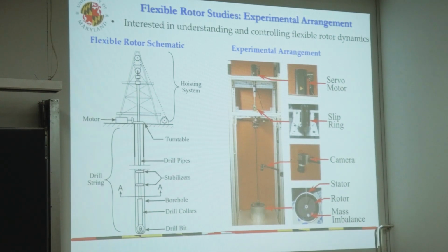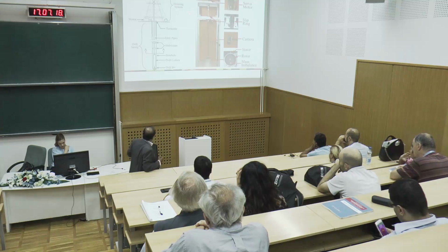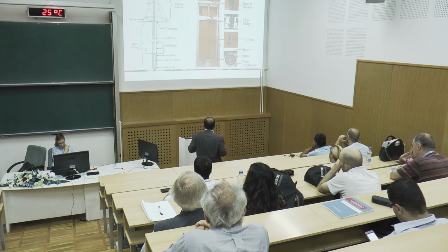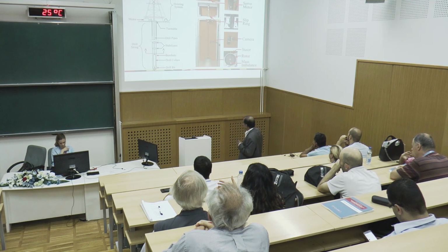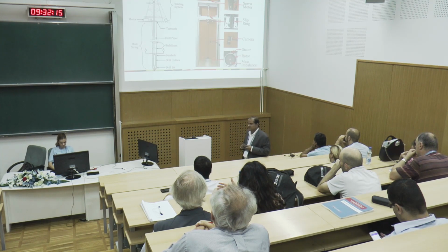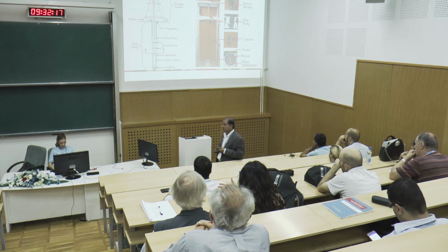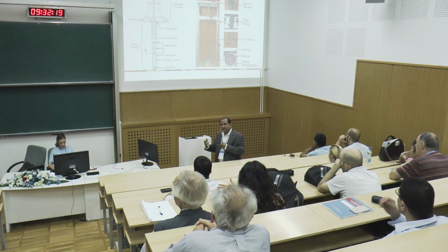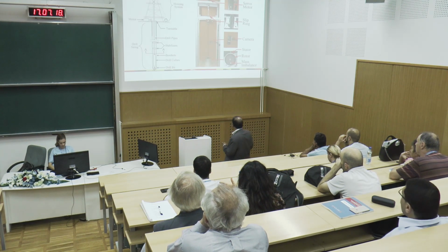So this setup, if you will, can be used to understand what happens between two stabilizers on a drill string that you saw in the talks yesterday. Of course, there's no cutting action in this case. In these operations, backward whirling is something that you'd like to avoid. So the question now is, with noise, can I move the response around from one response branch to another?